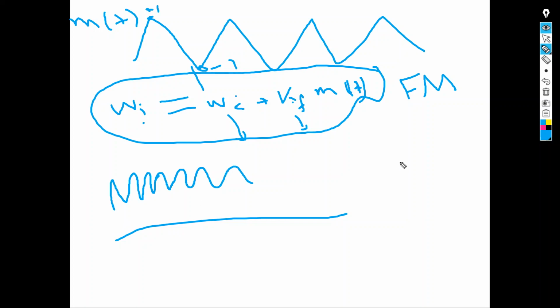Now you transmitted the signal and the receiver captures it. How can the receiver decode the signal back? The receiver uses a filter to tune to certain frequencies and map these changes in frequency to amplitude changes. The receiver has a kind of reference, the frequency starts with this value, and based on the value of the frequency, the receiver changes the amplitude of the signal.